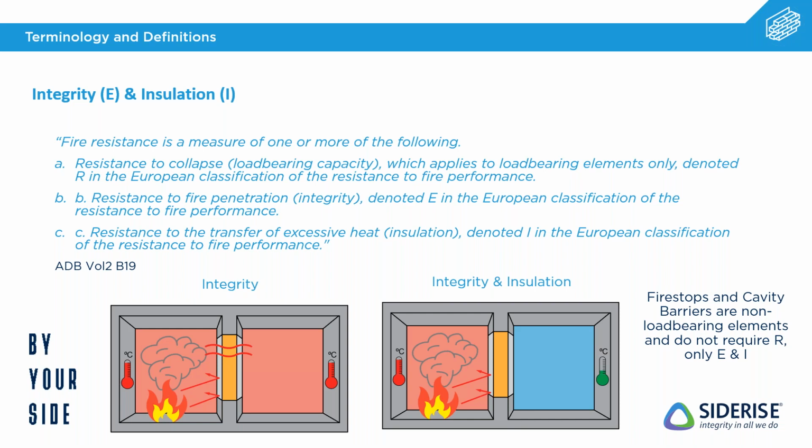You then have the actual resistance to fire penetration, or the ability to stop the fire getting through that product, and that's denoted by the letter E, known as integrity. You then have the resistance to transfer of heat, so the actual insulation of that product, and that's denoted by the letter I. Now, when we're looking at cavity barriers and fire stops, we're looking just at that E and I, that integrity and insulation ratings, and that's because they're not load-bearing elements.